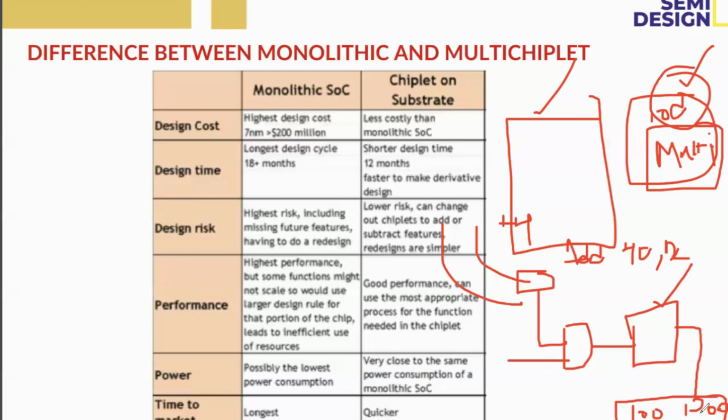But for a processor, everything is generated in binary format. So we cannot do the verification using SystemVerilog, UVM or any HVL or HDL methodologies. Here we are using C based.